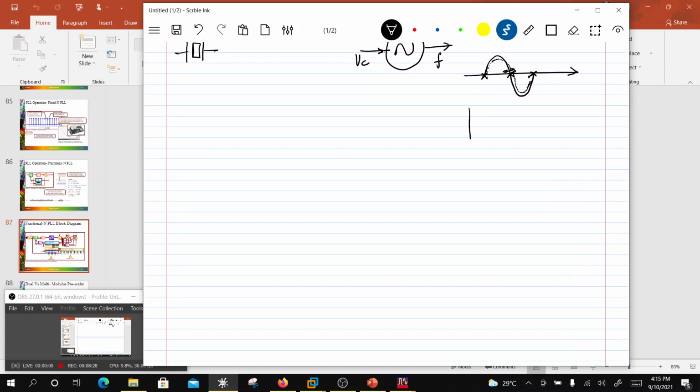Now when we talk of phase noise, we talk of single sideband phase noise, and what that means is I'm looking at a carrier which is FC, and then we are plotting offset on the x-axis, right? And then we are looking at the magnitude of the carrier. So this is the carrier which is of our interest, but then around this we have something which is not of our interest. So basically it decays, and it decays something like this.